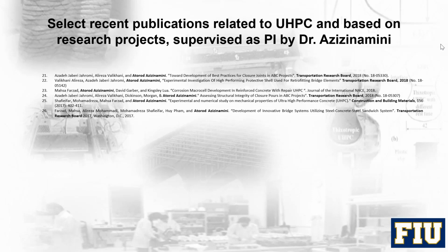Okay. There's a question here, and I don't know if this is about the 3D printing or your overlays. How would it work on the underside of a bridge deck? Shotcrete, will it stick? Yes, it does. We are doing a test on an upside down vertical wall. The one that I showed you was vertical. When you shoot concrete at speed, it sticks. We use VMA, a viscosity modifying agent, to modify the viscosity of the mix. That took us about a year to figure out how to modify the mix so that it sticks to the surface.